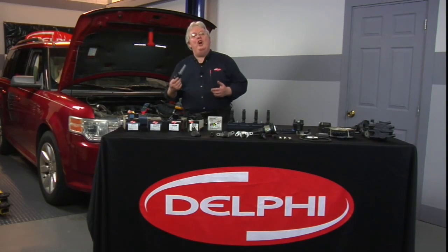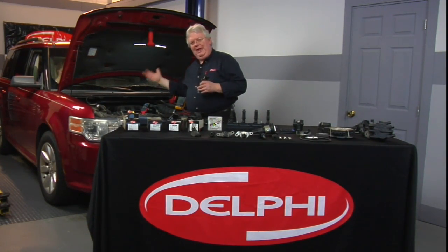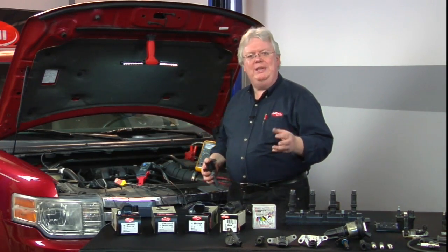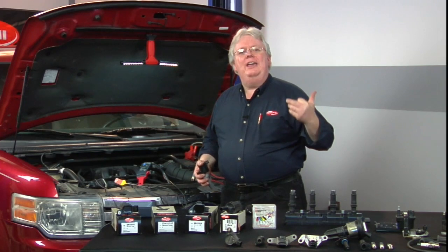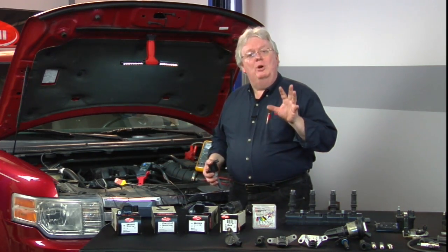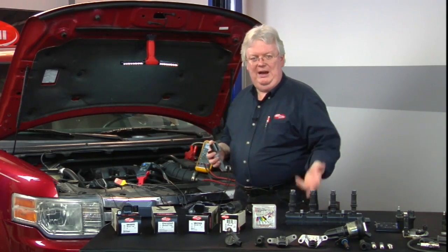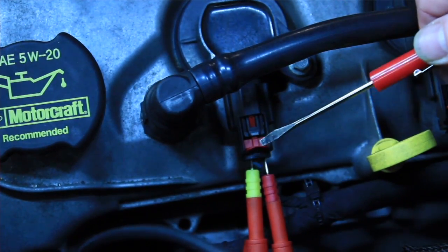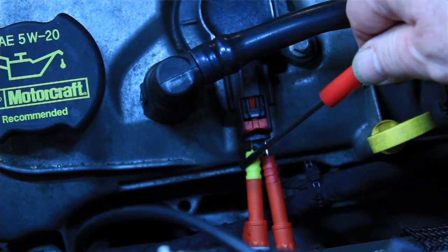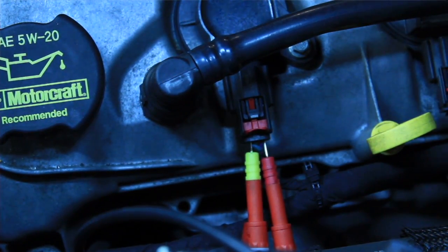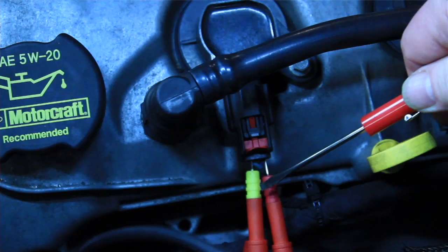Okay, time for some hands-on on the vehicle with a coil-on-plug 09 Ford Flex. Which cylinder is actually misfiring? That's why we had a broadcast last year that you can look up on the Delphi YouTube site and find all about Mode 6, because Mode 6 was really made for us to determine which cylinder is misfiring. Now what we're going to do here is look at simple power to the 2-wire coil-on-plug on key up. We're going to look at it two different ways, once with a meter, once with the scope. And of course, I'm using the back probe of the two connections.